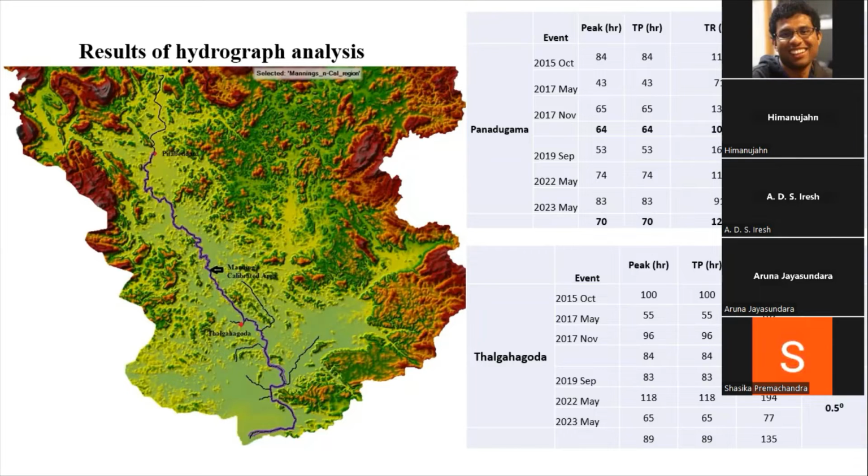So by analyzing various flood events, we can see that the recession limb has extended. The time period for the flood to reduce has been extended. That is a major finding. It shows that there is an impact. Of course, there is an impact of the salinity barrier when we compare the flood hydrographs of the before and after scenarios at both river gauges.